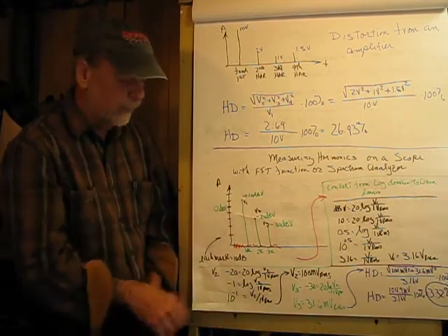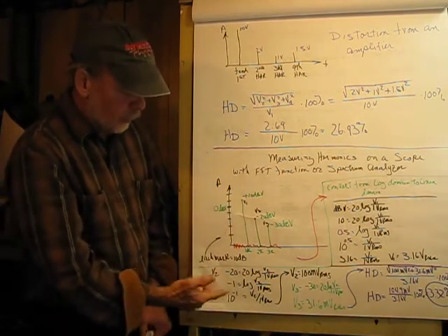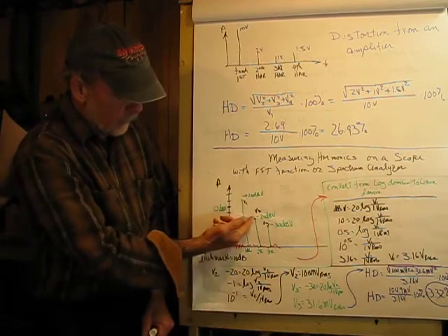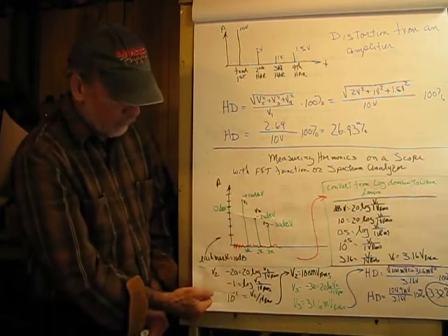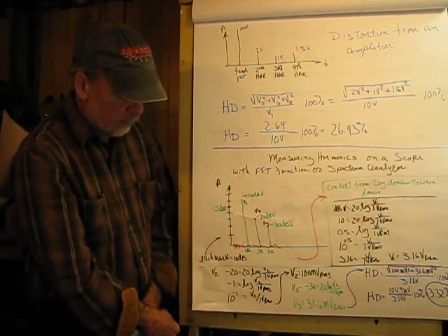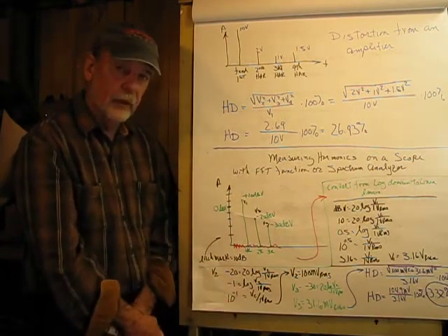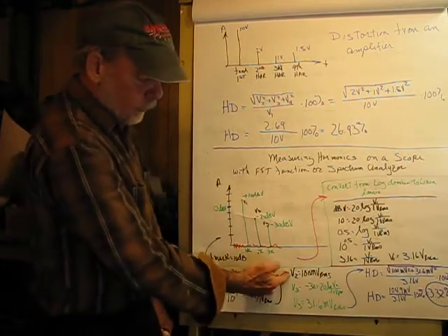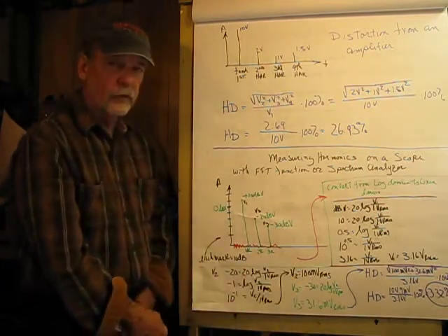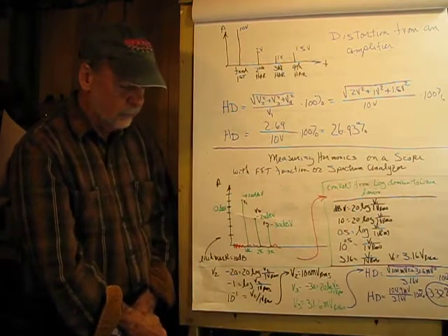But we've got it. Let's go on to figure out what V2 is, and that's negative 20 dBV. Sets up the same way. Doing the math is 10 to the negative 1 equals V2 over our reference, 1 volt RMS. And solving for V2 then gives us 100 millivolts RMS.